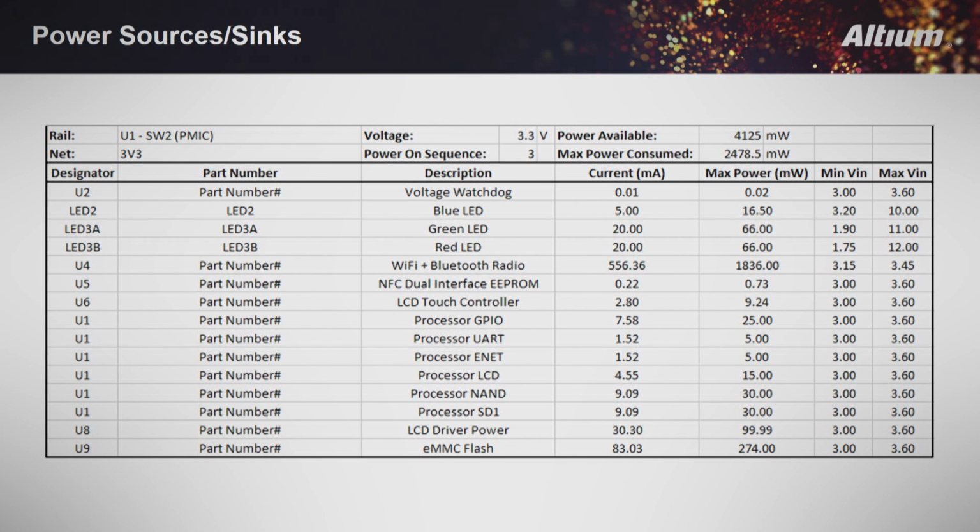So if I have it here, what you're going to do is either you're going to have this information in your schematics at your fingertips, or you're going to sit there when you're doing a PDN analysis and be looking up data sheets of individual components and plugging that information into the PDN analysis tool as you're doing it.